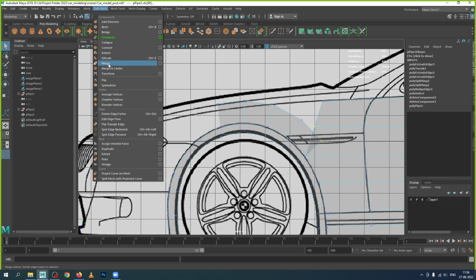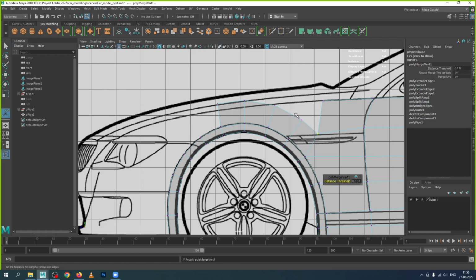Right click on this one, vertices, select these two, edit mesh, merge. I am merging the vertices. Two different points are there, I'm making them into one single point, using the merge option. What happened? It has merged. Now we don't have to merge this one, try to move it and balance this one now. Like this. You need to balance the line.